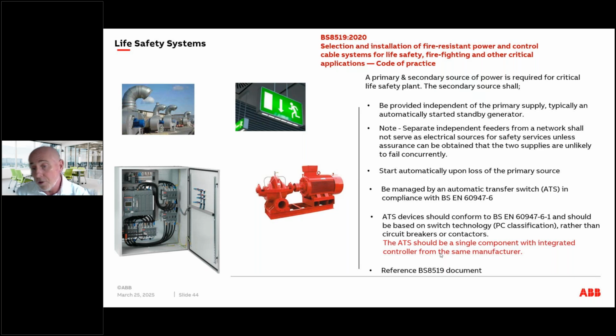Now, we all know that switch technology now is the PC classification rather than circuit breakers or contactors. So I mentioned when we looked at the classification, there's nothing wrong with circuit breakers, nothing wrong with contactors for the job of the application that it's been called upon to perform. But when it comes to life safety, the standard BS 8519 says you cannot use circuit breakers or contactors. It must be a switch technology.